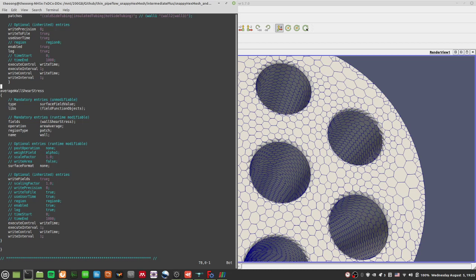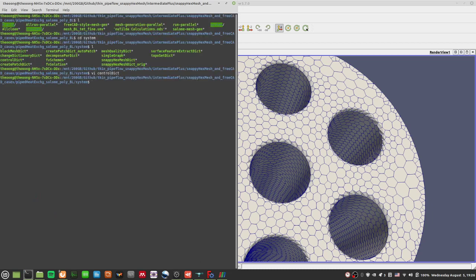I'll do it on the cold tubing. So I'll do the cold side tubing to be my only place where I do wall shear stress. Of course, I can do it for all of them, the side tubing, and that's it. So that's all I have for you this video. Thanks for watching. This is roughly how I do my boundary conditions.